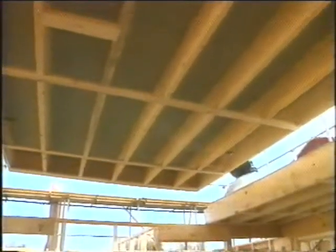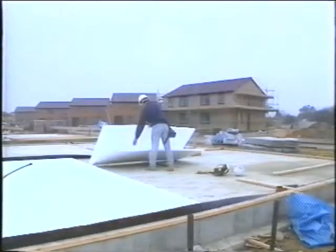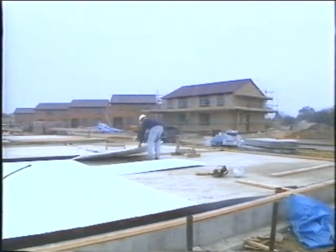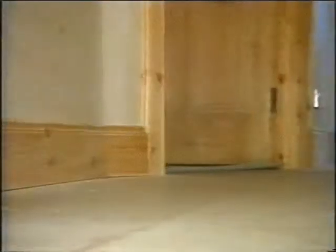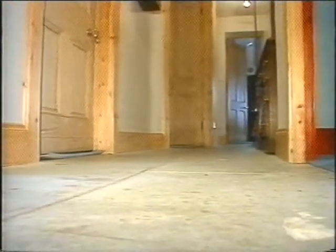If it's a suspended timber floor, materials can be laid between its joists, just as they are in the roof spaces. If the floor's solid, however, it's more difficult and much more expensive. It can be covered with insulating material, which then has chipboard or some other flooring laid over it. But a barrier's needed to make sure that water vapor doesn't condense on the cold concrete.